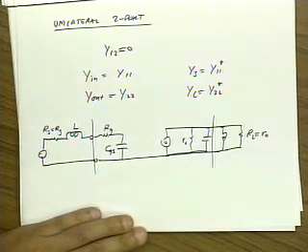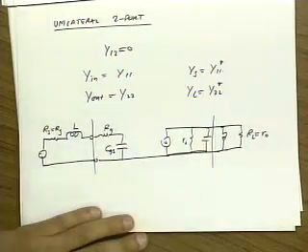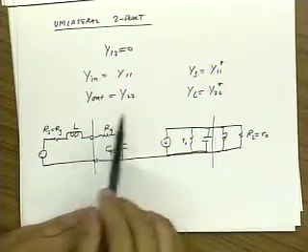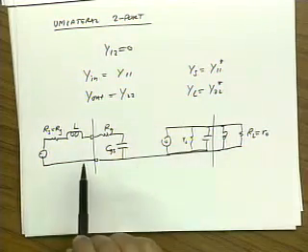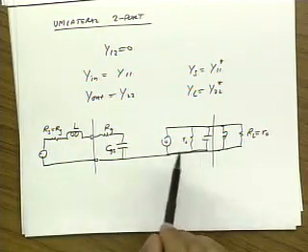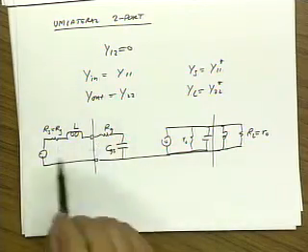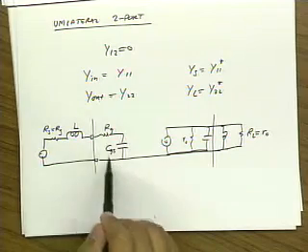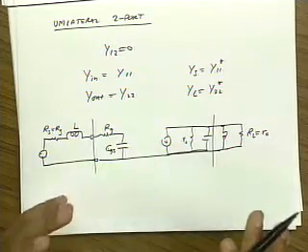Okay, and as you see, they form natural resonant networks. This one forms a series resonant network. This one forms a nice parallel resonant network, what we studied a couple lectures ago. And so once we have a resonant network, of course, you know that this condition for optimality is only obtained at one frequency exactly, at resonance. And so we want to make sure the input resonant frequency is equal to the output resonant frequency. And you'll also note that if you just design a circuit this way, you have no control over the Q. The quality factor is already set by the input admittance quality factor, right? So if I can't control the Q of the input and output, I just get what I get.